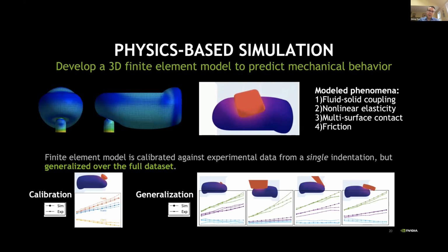So what he did was the following. He took the finite element method to, first of all, predict all the deformations. From those, he then predicted the resulting overall 3D force that would be applied to the BioTac, and that he was able to compare to the measured forces through the 6D force torque sensor placed underneath the BioTac.